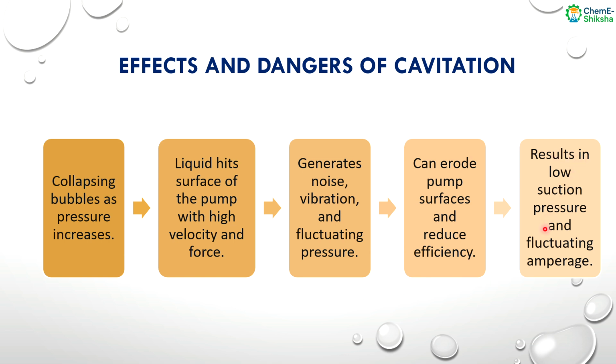As the vapor bubbles occupy most of the area, the liquid flow becomes erratically low, and the pressure also becomes erratically low. The suction pressure and amperage also become low. So these are the effects and dangers of cavitation.